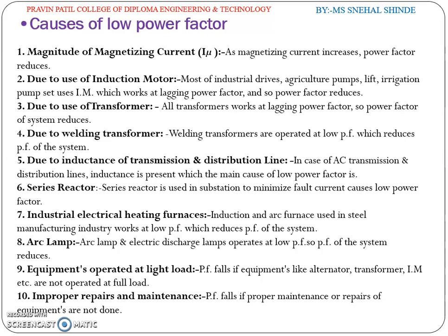So the power factor at which a motor operates falls due to improper maintenance and repairs of motors. In repaired motors, less wire is sometimes used than in the originally wound motors. Therefore, in such motors, leakage of magnetic flux increases and power factor of the motor decreases due to the large magnetizing current. And due to increased supply mains voltage, which usually occurs during low load periods such as lunch hours and night hours, the magnetizing current of the inductive reactance increases and the power factor of the electrical plant as a whole comes down.